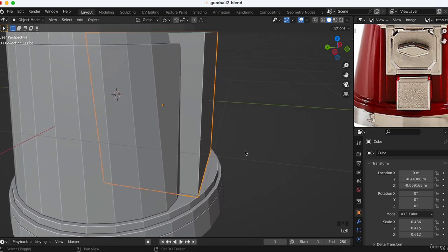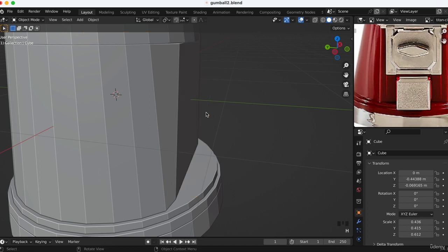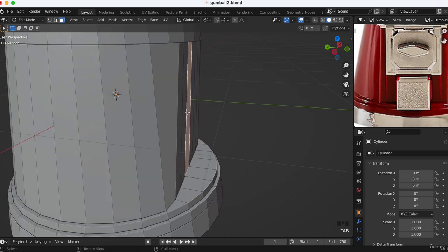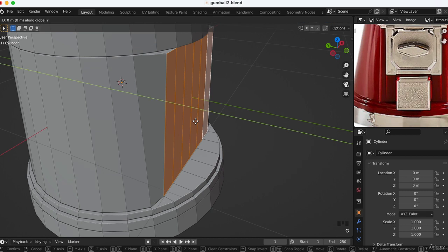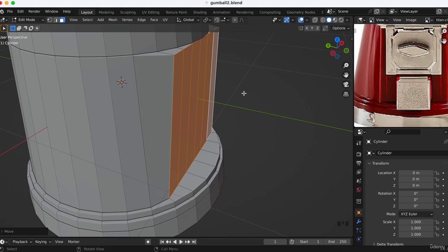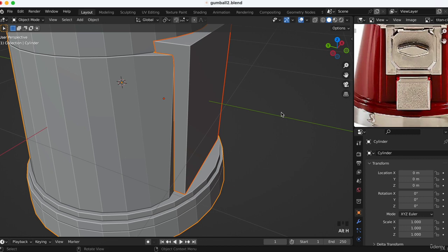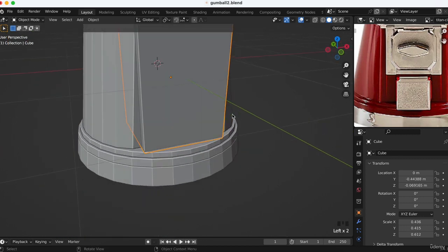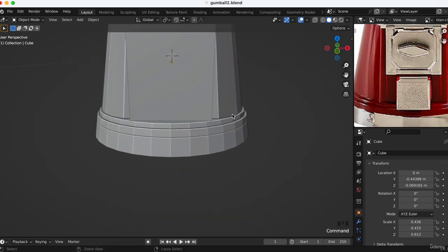and I think the flat part, we can make it, we can move it. So we can select the cube, we can press H to hide it, and then click on this, Tab, we select Shift, click all of this, we can move it G, Y, like this. We can put the cube back, so we do Alt H, and then it is here. I think it is pretty good like this.